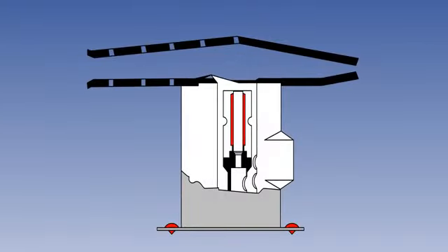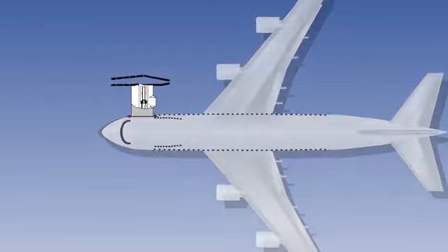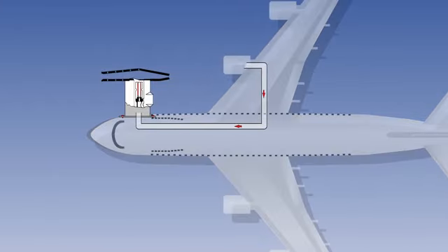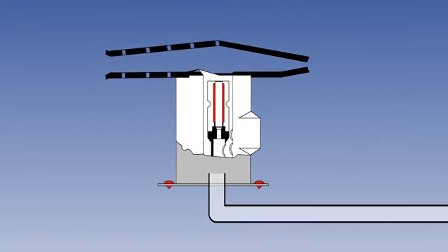Without forward movement of the aircraft, air within the sensor casing can stagnate. Stagnated air could give a false indication of the outside air temperature. To re-establish an outside air flow within the probe, an air-to-air ejector or aspirator is used. The principle we can see in operation here is that pressurized bleed air is being drawn from a compressor stage of a running engine or auxiliary power unit and is being fed through the aspirator. This creates a negative pressure differential within the sensor casing, which draws fresh outside air past the sensor element.